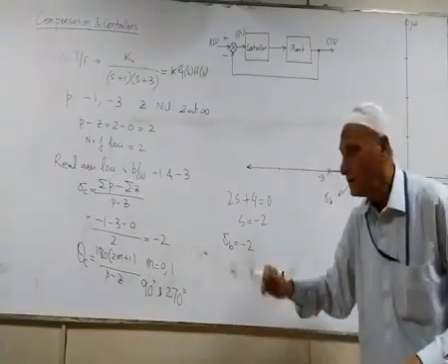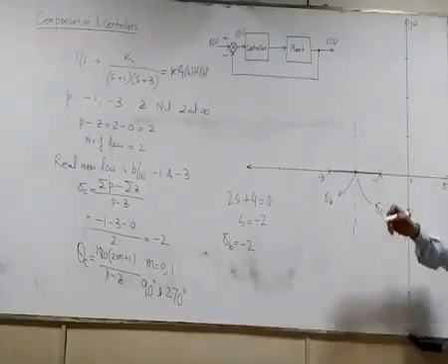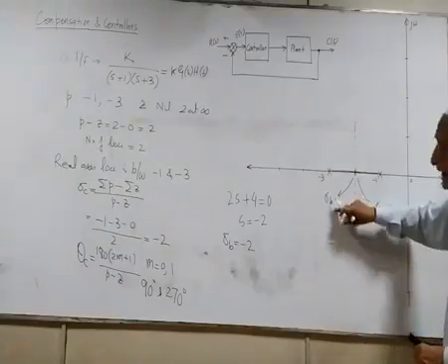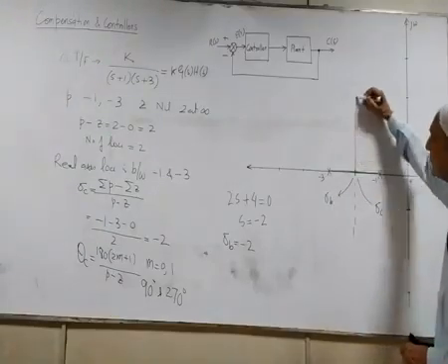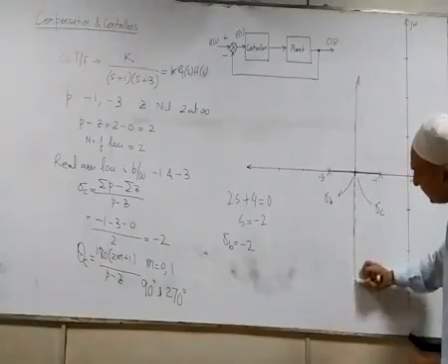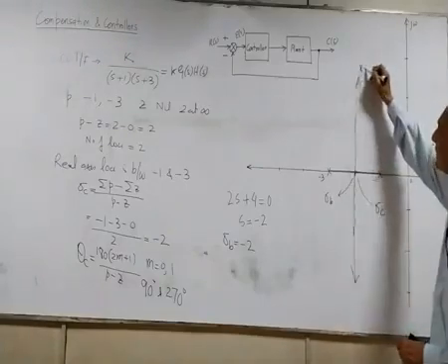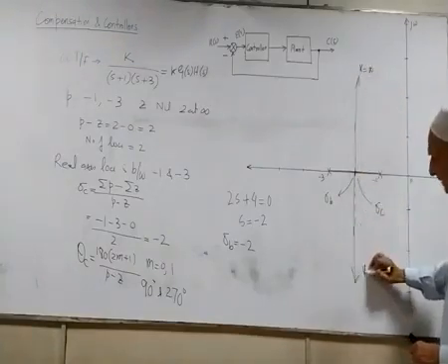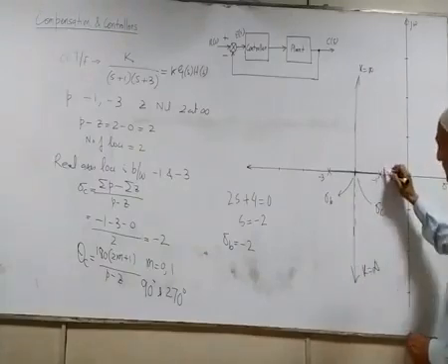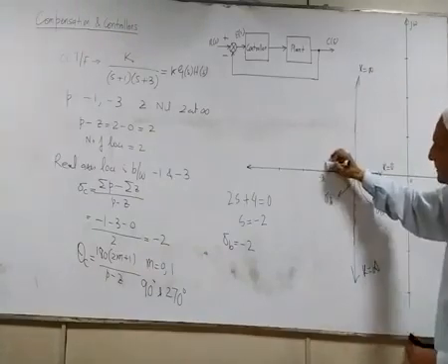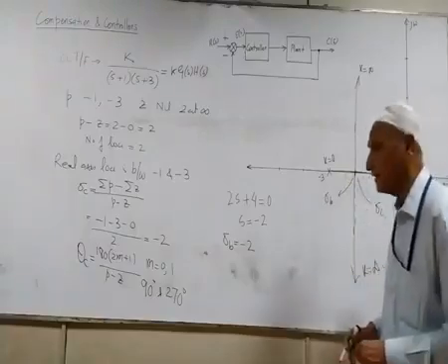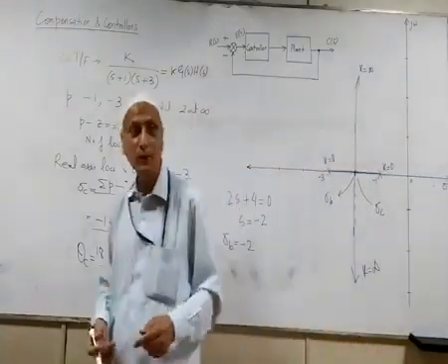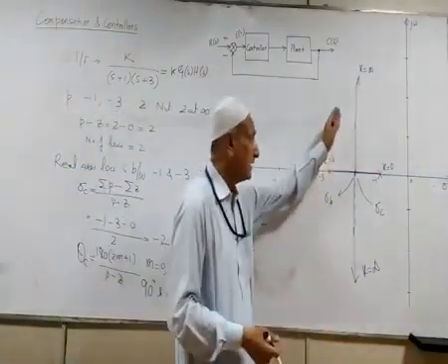Now the root locus will take off from this breakaway point and move in search of the zeros at infinity, where the gain is infinity. These are the open loop poles where the gains are 0, and the locus is looking for the two zeros lying at infinity.